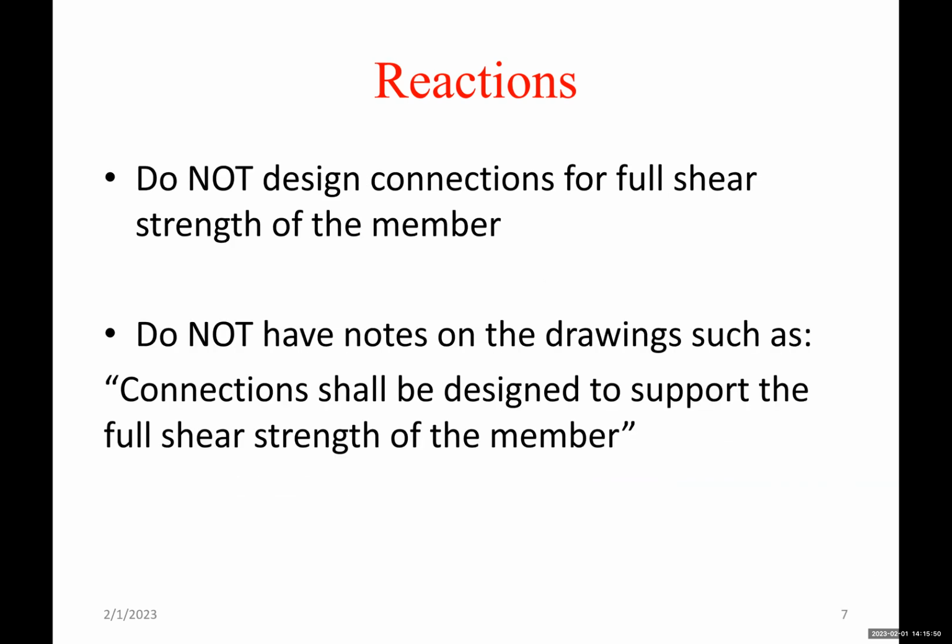So do not design connections for the full shear strength of the member. We just talked about that. Do not have notes on the drawing such as "connections shall be designed to support the full shear strength of the member." Full shear, that's 100%. So I told you I've seen 40, I've seen 50, and I've seen 60% in design offices.